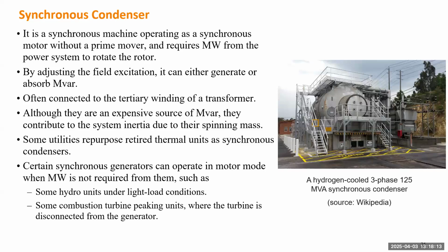Later we'll talk about another tool based on power electronics. But usually those control devices are more complex. So if you want to first verify whether the idea of placing a voltage controller there is good or not, one very easy method is to just place a synchronous condenser there.